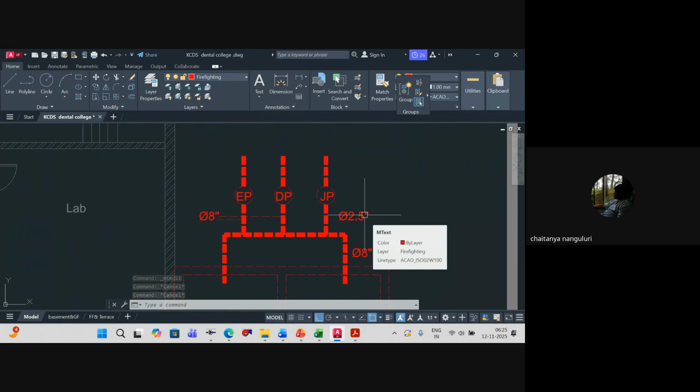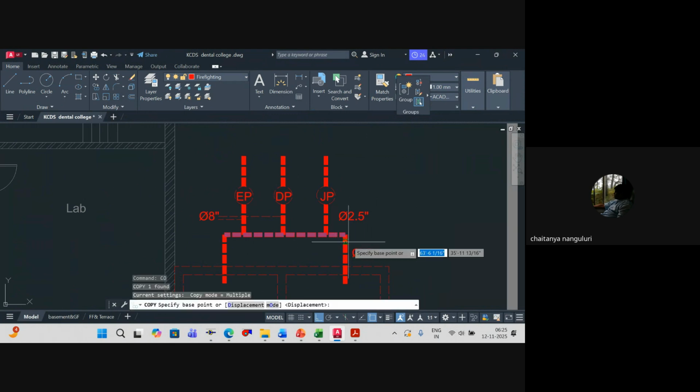Then we have to worry about the next one, which is your discharge. Your discharge velocities will be around 8 FPS, so your discharge manifold could even be 6 inches.